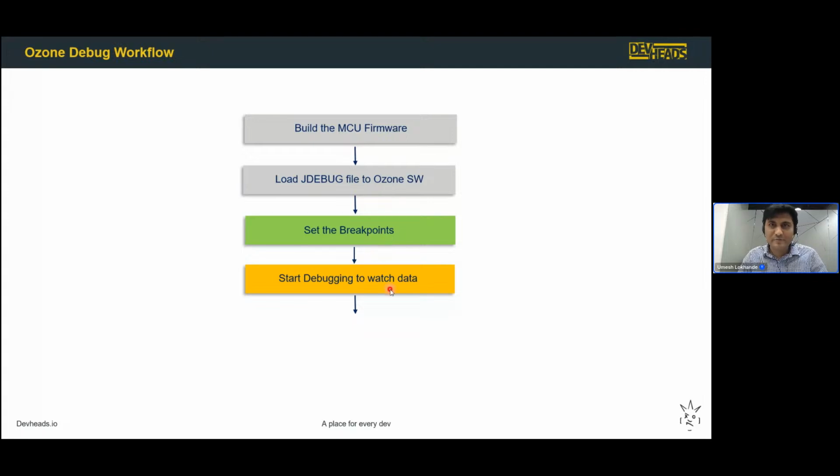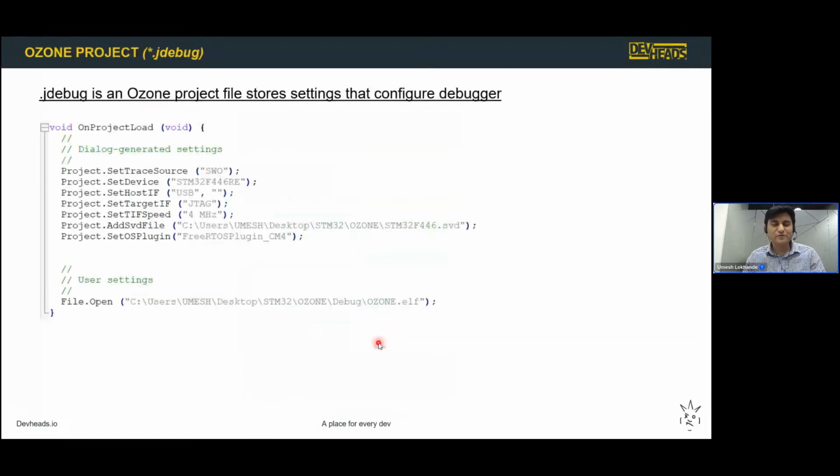And one of those things would be a data watch window. And then we can also visualize the RTOS window. We have a dedicated RTOS window, and there you are able to do RTOS-aware debugging. I remember in the previous engineering hours, somebody asked this question, like, what if they want to get a finer detail of the RTOS? Let's say they want to know about the priorities of the tasks, or maybe the events, the states, the mutexes in the RTOS. Everything you can track down there. Okay, so that's a great thing about this RTOS window. We'll get into that, by the way.